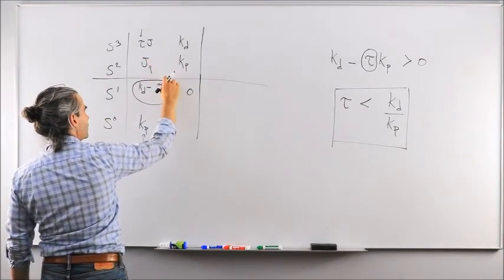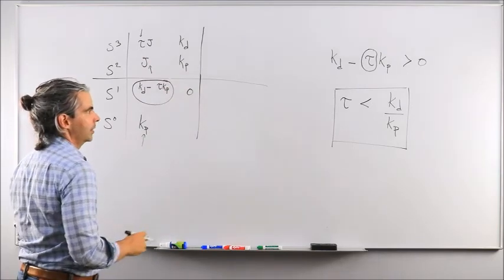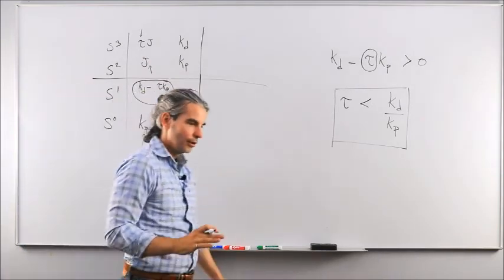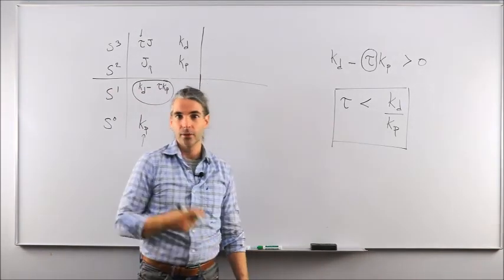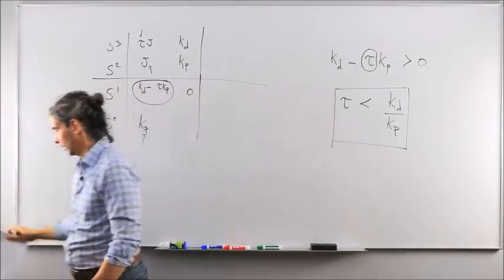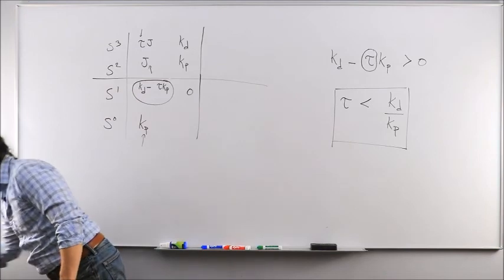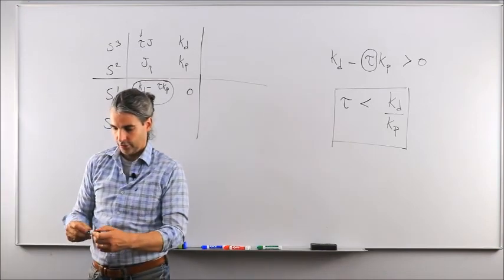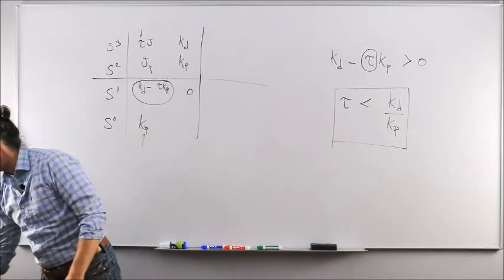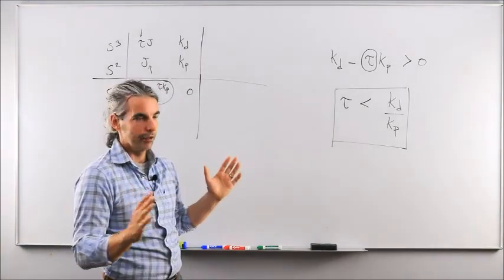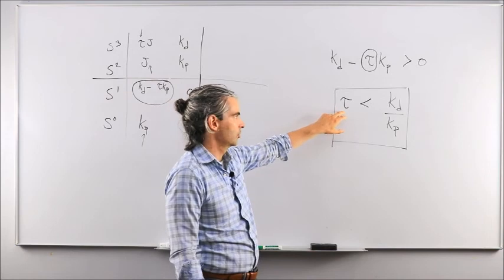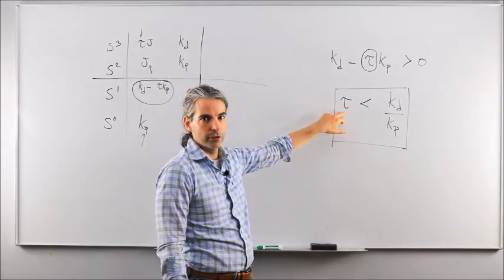So you get 1, 2 sign changes, and that would mean that the entire closed loop system will go to garbage because you're driving poles onto the right-hand side of the complex plane. Guess what? You've lost your job because you've been creating the cause of the loss of your spacecraft. Multi-million-dollar mission done because the actuator was too slow to respond to the controller's demand.